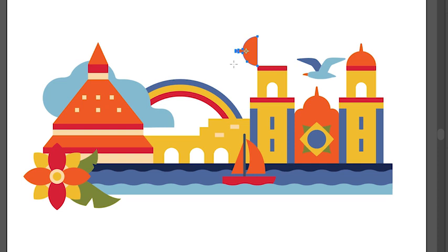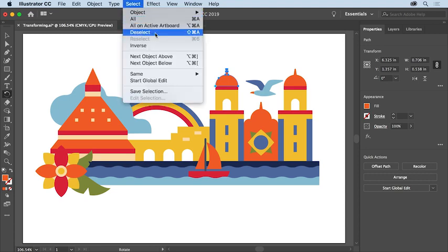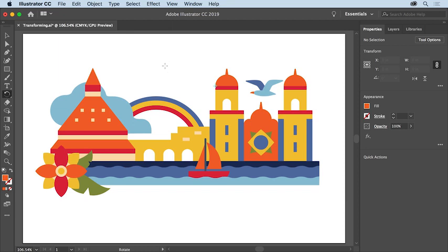To move this point, click and release in the corner to set the reference point, or where it will rotate around now. Then move the pointer away, and press and drag anywhere out here to rotate the shape. As you drag, press the Shift key to constrain the movement. When it's in place, release the mouse button, and then the key. So that you can see all the final artwork here, you'll deselect everything. So choose Select, Deselect.